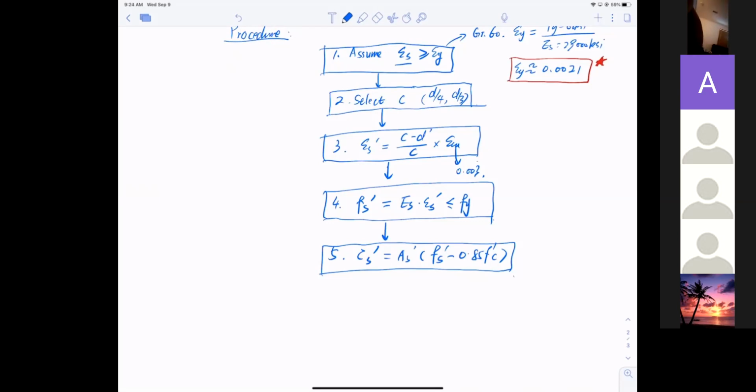So you actually have a lateral deformation that will crush the concrete in that direction. Okay, I see now. So we don't want it to ever yield. The compressive reinforcement is just acting as an elastic material there. We only want the tension side to yield, because as tension happens, the concrete will lose strength. Only the steel will take care of the tension force, and we can let it yield because stretching will not cause lateral deformation so much, isn't it?